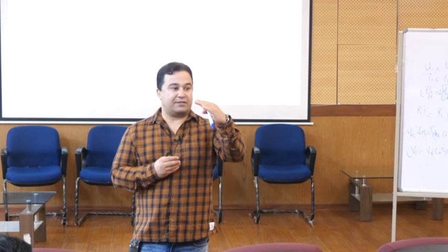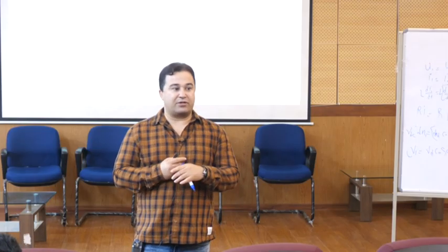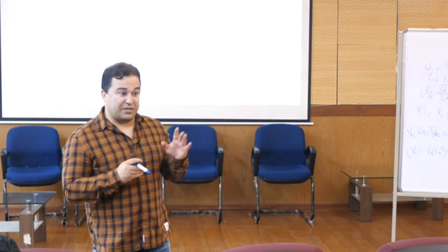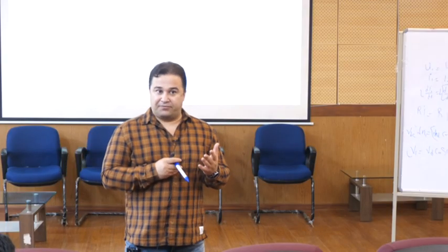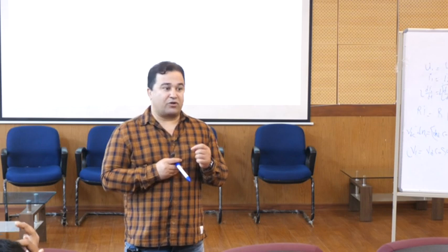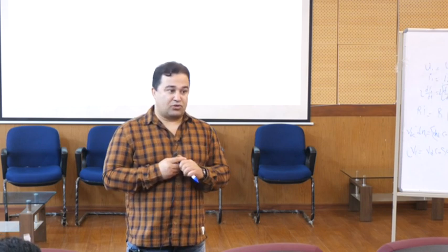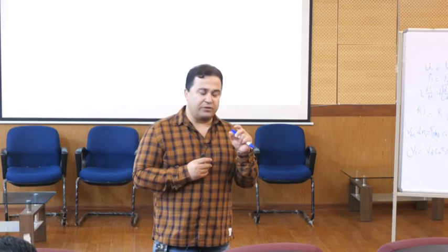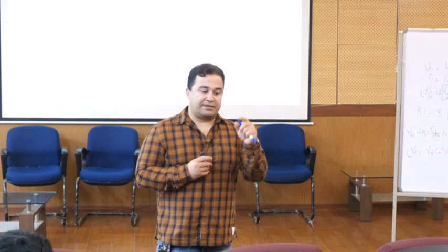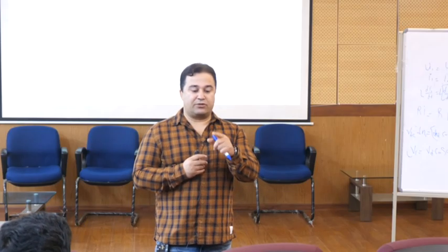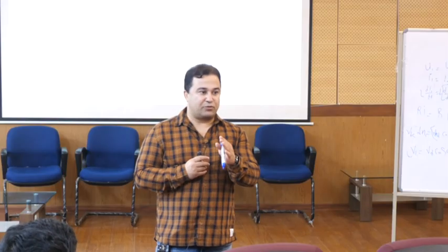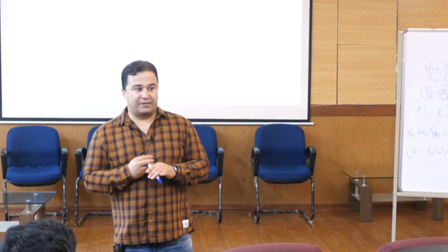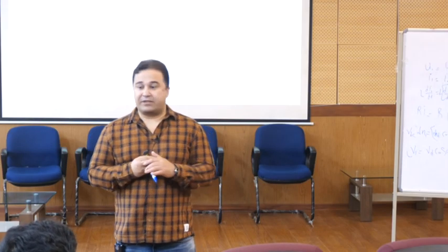And if VD is DC and VQ is equal to 0, I say okay, now nobody can say this is a problem, because if you program it the wrong way, the Q will not be 0. So immediately when I run the code, I see the VQ is 0. It means that up to here my simulation is correct. So you should have some idea about the stages that you are proceeding.